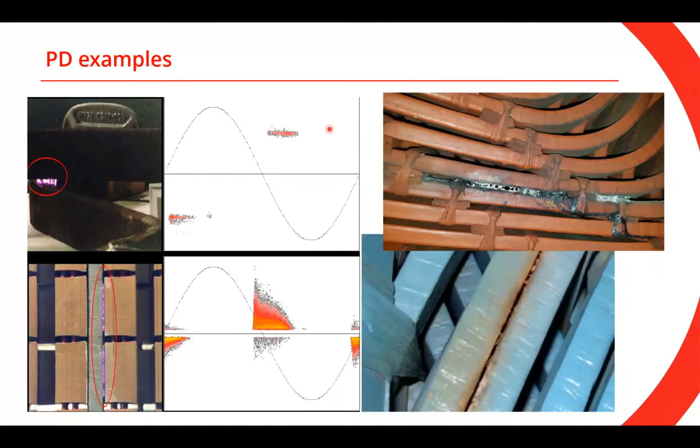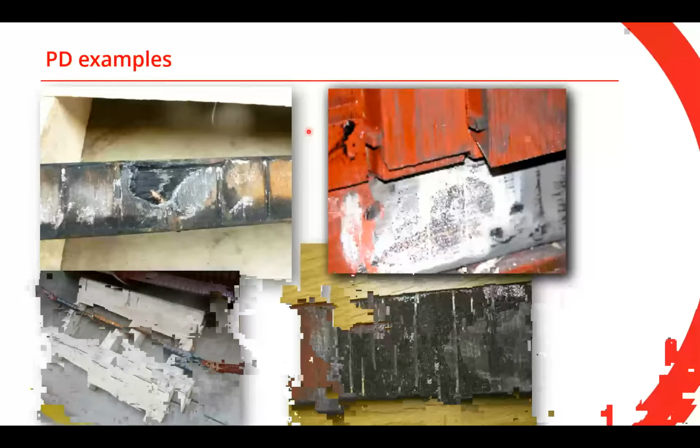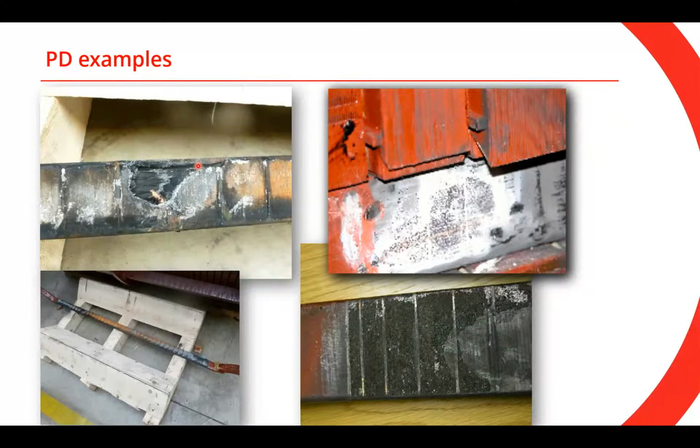And again, what's amazing today is that by looking at the partial discharge pattern, you can say where that partial discharge is taking place. Like here, you can see that little cloud. Again, amazing stuff. All right, I like those pictures because this is where the partial discharge occurs more often. This is the surface of the stator bars. And you can imagine when everything vibrates, as we've discussed with the team, that surface that was supposed to have semiconductive paint has been damaged, causing partial discharge to occur.